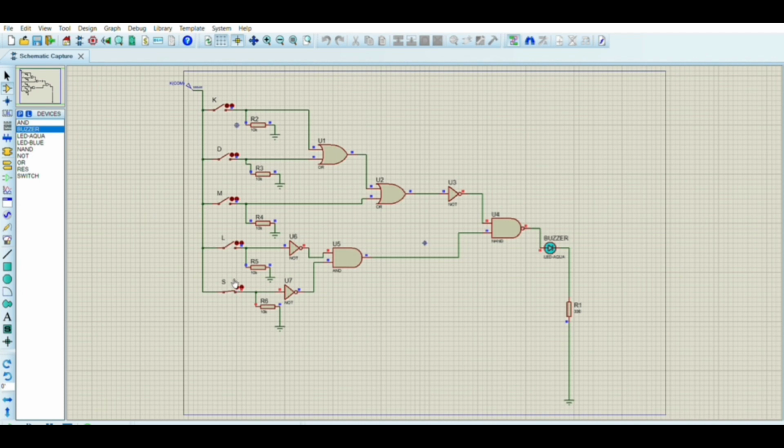Use an LED to display the output of the OR gate from step 5. If the LED is on, it means that one of the conditions for activating the alarm has been met. The buzzer should be activated. This should give you a digital circuit that can detect the driver leaving the key in the ignition when the door is open, driving without buckling their seatbelts, or leaving the lights on when the key is not in the ignition.